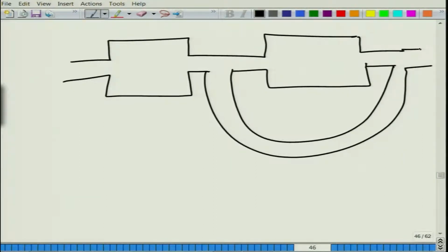Okay. So, what happens now, the acoustic waves have more than one choice of propagating. At the moment they come to this junction, they can either propagate downstream here or they can go here, and then when the waves come here, they again have a choice of constructive interference and destructive interference. So, this can be your muffler 1, muffler 2, and what we are doing here is providing an additional path through which the waves can go. Such things are called multiply connected mufflers, or things with non-unique wave propagation path.